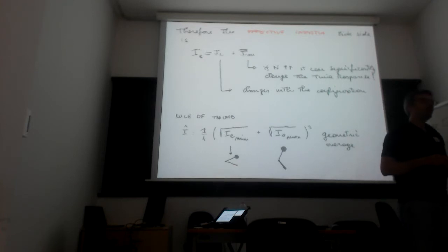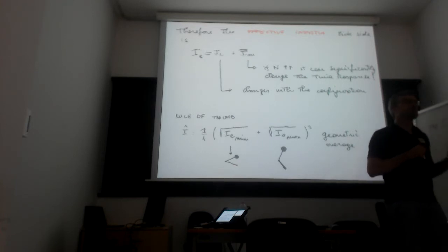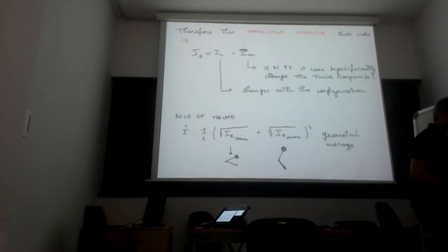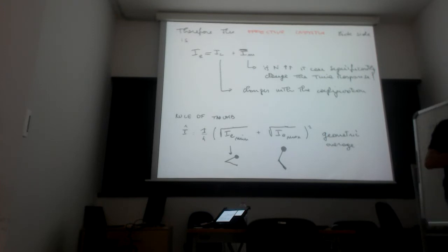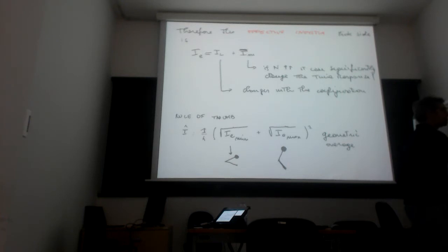But if you take care of this and do it in a smart way, for example applying the 180 volts only during the stance, and then going to 0 during the swing, the current starts to increase but doesn't have time to reach the melting temperature, and then it goes down. Then it increases, it goes down.